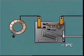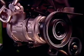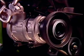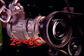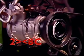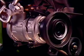This increased temperature is applied to the fluid in the capillary tube, causing an increase in pressure at the bellows. The bellows pushes on the pivoted frame against the spring force and closes the contact points to complete the circuit to the compressor clutch once more. Circulation of refrigerant is resumed and system operation recommences. The thermostat usually cycles the system between a minimum of 2 degrees centigrade and a maximum of 8 degrees centigrade to maintain the evaporator at the required temperature.